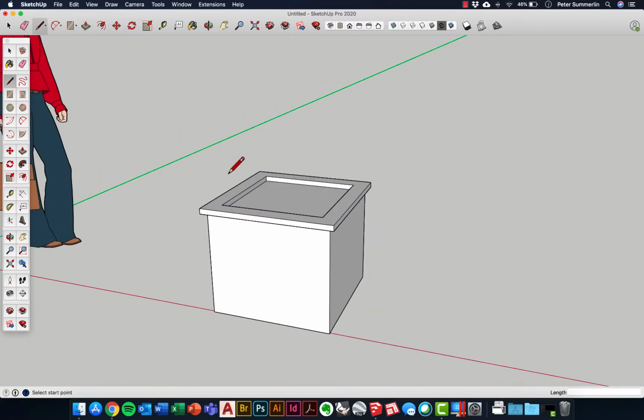You also notice that you have the pencil tool. It allows you to kind of in space create some shapes. Maybe you want to do something that's a little more custom, and you can create that face and push-pull from there. I've also got the selection tool right here. If I single click, it just allows me to select the face and delete it. I'll undo that.